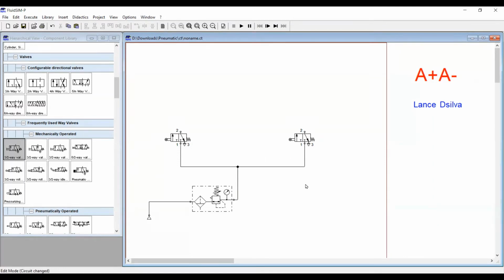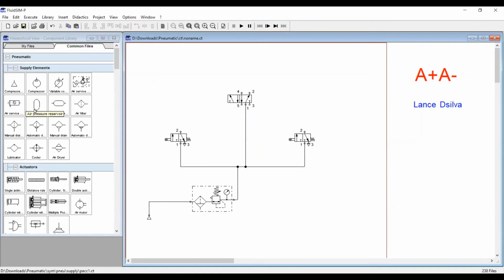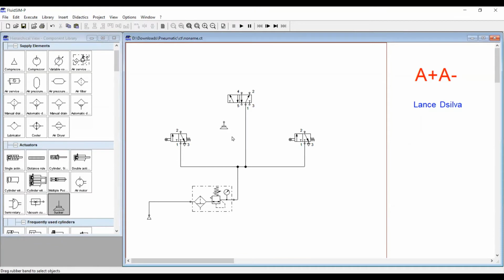Awesome. Now let's go on to the next step, that is we require a 5 by 2 configurable valve. So I'll take the 5 by 2 configurable valve. Now we want to give input. These are not input lines for the controllers. Remember, this one is for the air pressure, and these two, as we can see, are for removing the air, that is the exhaust. For joining this, you can use a silencer over here, as we can see down here. We have a silencer. The air which is supplied has to come back. It comes back through the silencer. Now let us connect it over here.